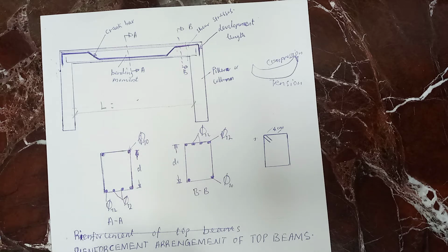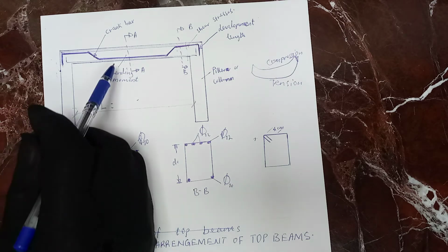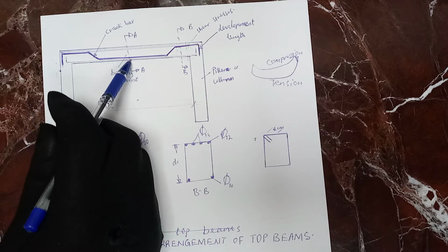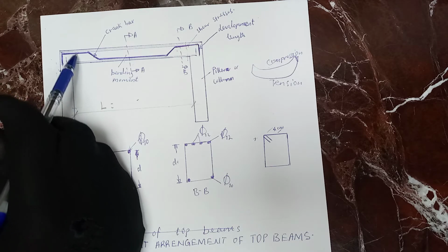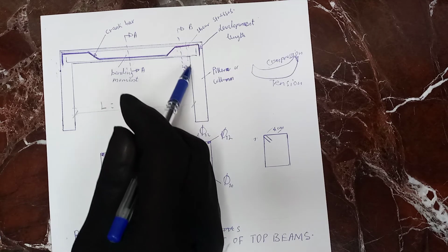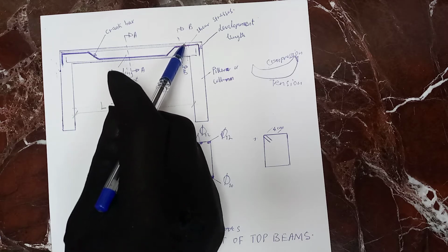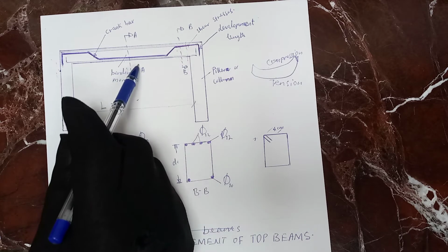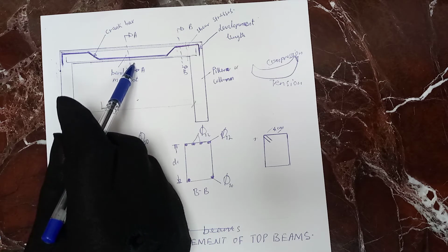It also depends on where you are using it, but it should be at least rod 12 to resist the bending moment. And as it is resisting the bending moment here, it is also working here to resist the shear stresses, because this is where the shear stresses will always occur, from these corners near the support. The supports are the pillars. So the shear stresses will always occur towards the support, and the bending moment will always occur at the middle or at the center of your beam.